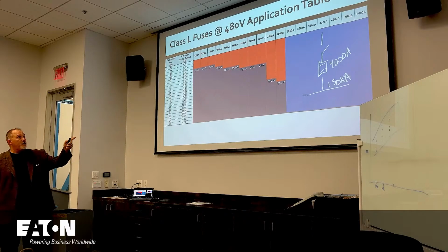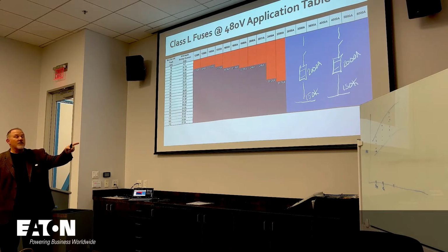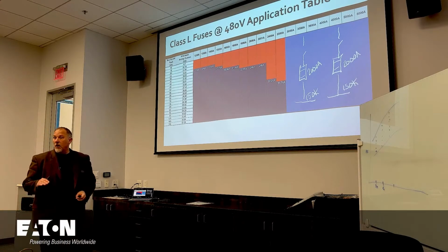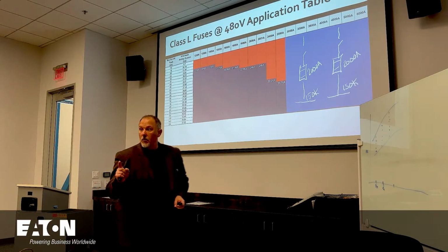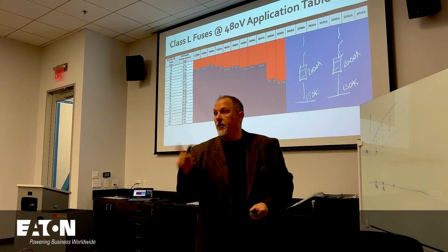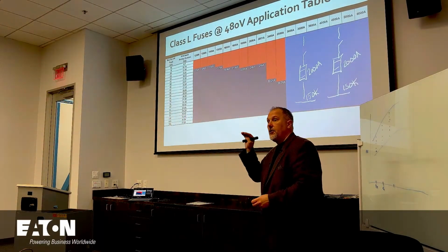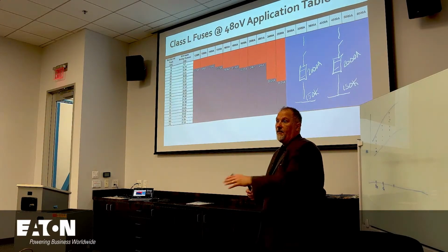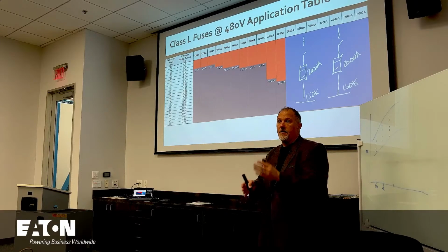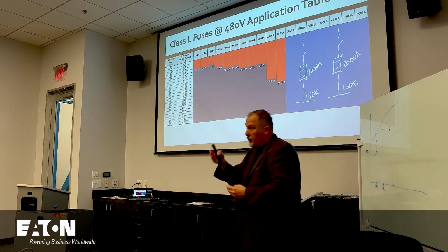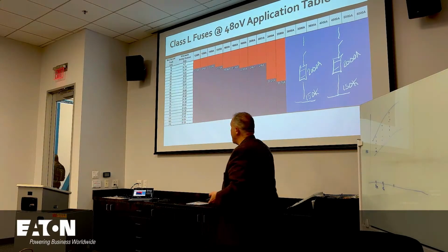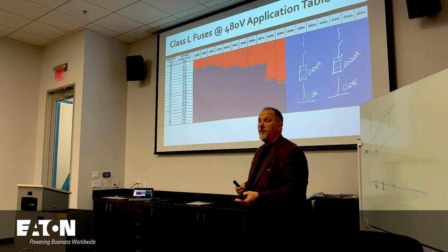So the other thing you can do is split that into two 2,000 amp services. Now you're in here, and as long as your fault current is greater than 24,000 amps, you'll meet the requirements of the code. You'll be in the 0.1 second clearing time, and you don't need an arc reduction technology because your fault current is high enough. Same thing for breakers, right? If you compare the time current characteristic curves, you can use the instantaneous on a circuit breaker. You can use the current limiting nature or 0.1 seconds clearing time for the fuses.